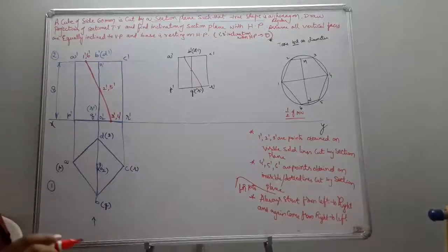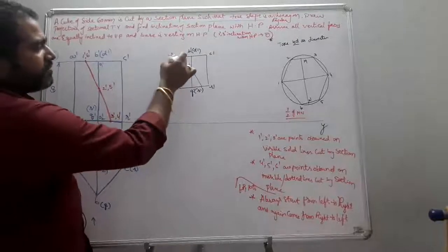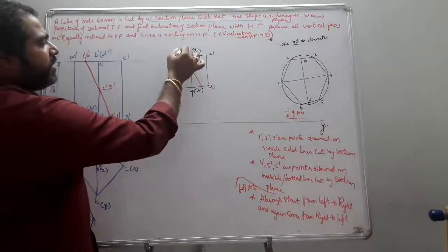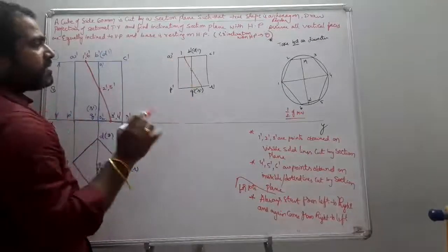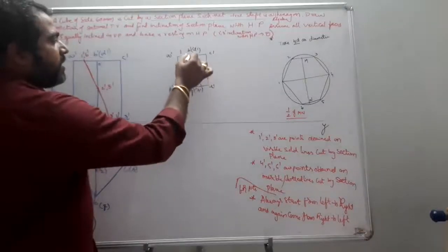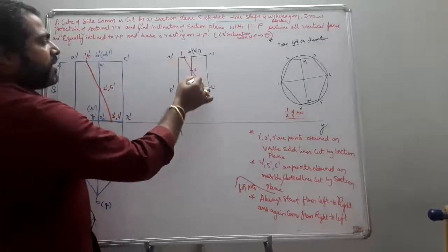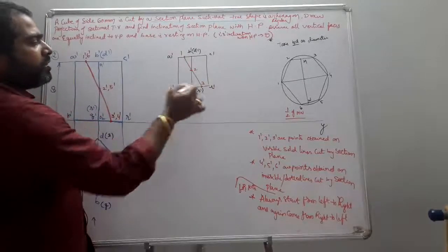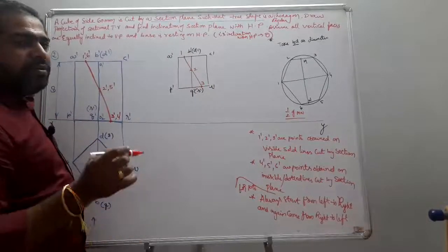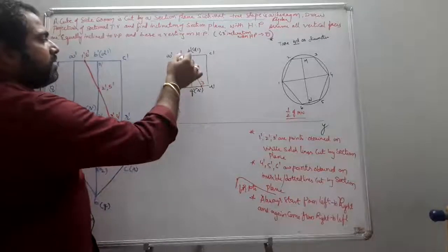Okay. So tell me the numbering first. Always start from the extreme left position. What is the extreme left? This was the extreme left. My points are going to be here. It is one, first point. It cuts the AB edge. Next, this point that cuts, it cuts BQ. This is 2. Next, this cutting plane cuts it here. This becomes your 3. Okay. 1, 2, 3. Next, what about the next point? That is 4 point where it is to be obtained.